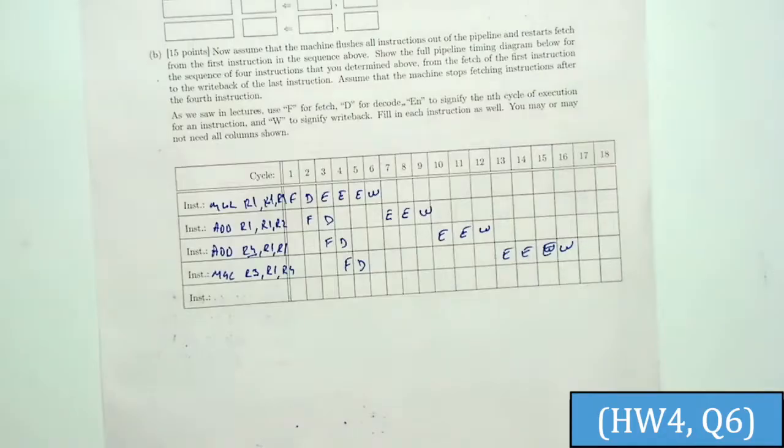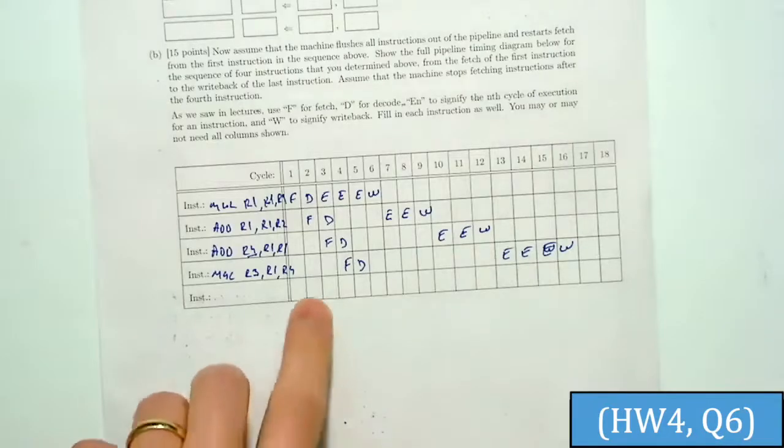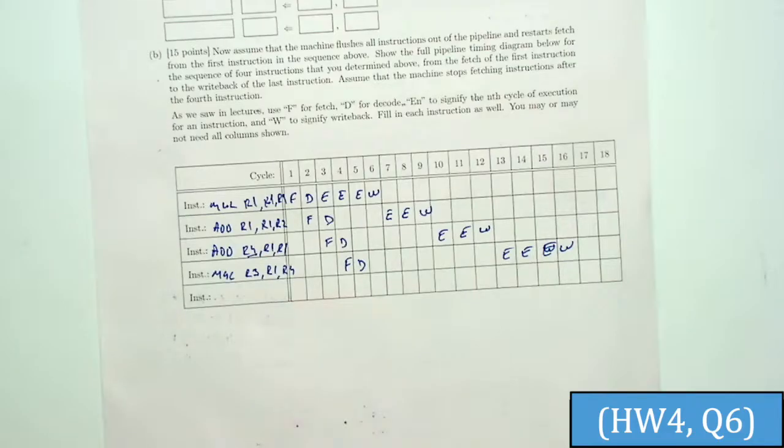I don't see how the third instruction could get it to decode. No, wait. It leaves decode stage and goes to reservation station. So decode stage is free again, right? Yes. Okay, then I understand. So this is slightly different from in-order execution, where usually we do the register fetch, fetching the source operands at the decode stage. So here, that's not happening at decode, right? So you are not accessing necessarily the register file at decode. You are just allocating a reservation station entry and filling it accordingly with all the dependencies.